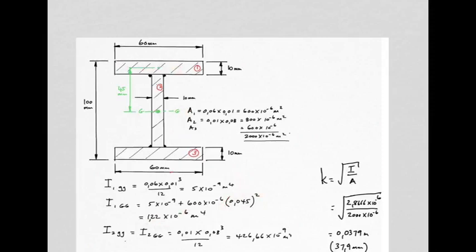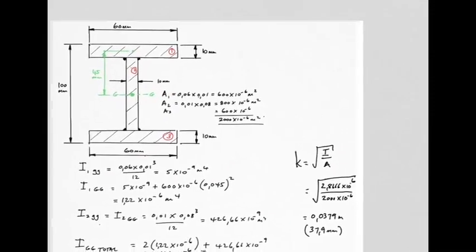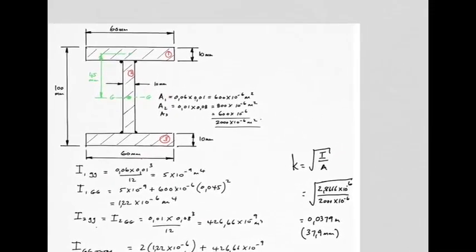That is the second moment of area of shape 1, not about its own axis, but about this axis here, 45mm away. Right, then we move on to number 2, which interestingly enough is easier than number 1 because its own center of gravity or centroid coincides with where you want the answer. So you're simply going to say I2GG is the same as I2 capital GG because it's already there.